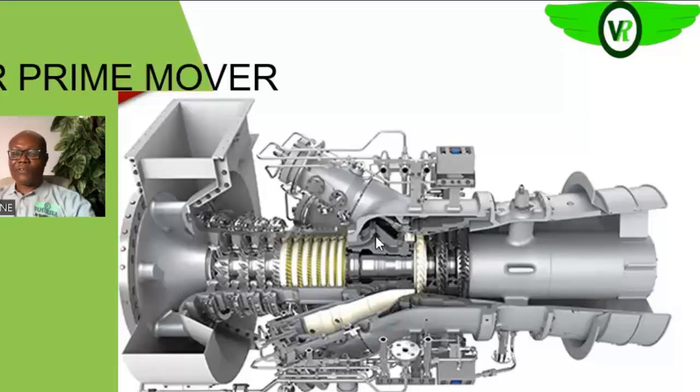Fuel is injected into that compressed air, and the fuel-air mixture is ignited. As it burns, the combustion product has a very high energy content. That high energy combustion product is then channeled through the transition piece into the turbine.